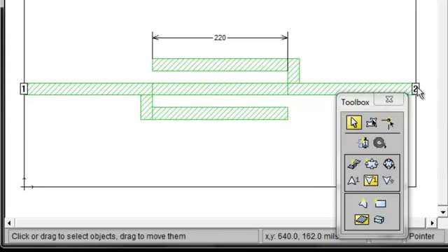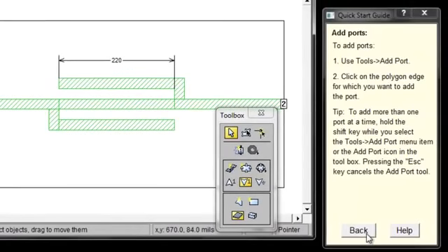If I don't put a port on a piece of metal that touches the edge of the substrate, remember it's shorting out on the Sonnet box wall, so that's in effect creating a short circuit of the stub or of whatever line is connected to ground.